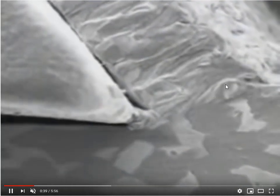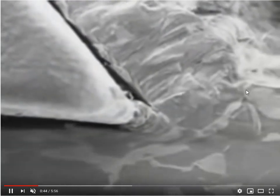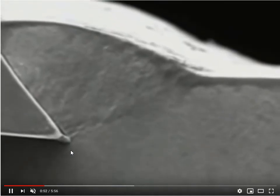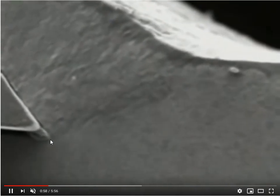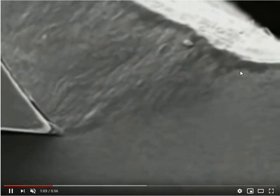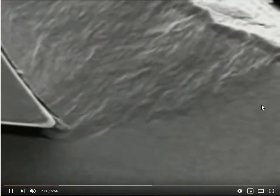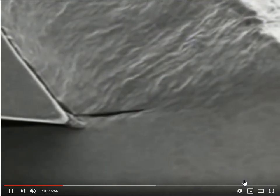Okay, and this area here, this shearing zone, this crush zone, this is where you're getting your plastic deformation. So some of the material underneath is actually being crushed plastically, but some of it's being crushed elastically, and it will kind of snap back. But in this area is plastic deformation. And if you notice, if you draw a line across here to the top of the material, the thickness here, the chip is actually thicker than the depth of the cut.